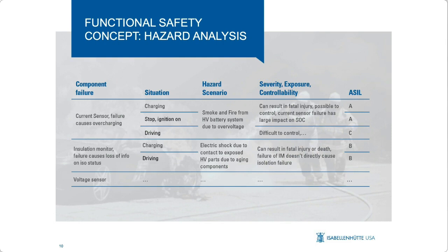A different component failure would be the failure of the isolation monitor. This failure could cause a loss of information on the isolation status. Also, this situation could occur in charging mode or while charging, and also during driving. The resulting hazard here could be electric shock due to contact, exposure to high voltage parts due to aging components.